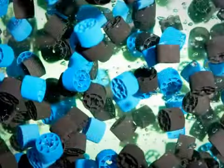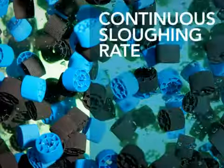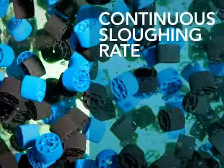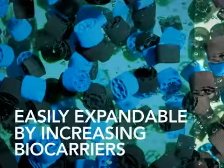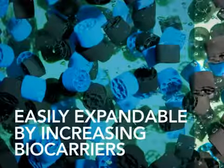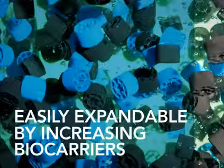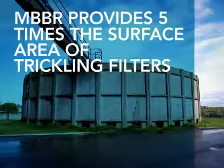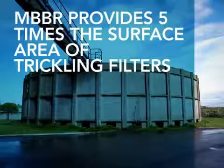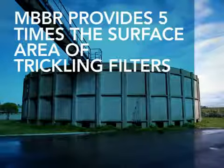The HeadWorks Bio MBBR aeration and mixing processes produce a continuous sloughing rate, which maintains a more active biofilm. Treatment capacity can easily be expanded by increasing the fill fraction of the biocarriers within the reactor, as much as 70% by volume. At equal levels of BOD removal, HeadWorks Bio's MBBR provides up to 5 times the biofilm surface area of a trickling filter, using less than a quarter of the reactor volume.